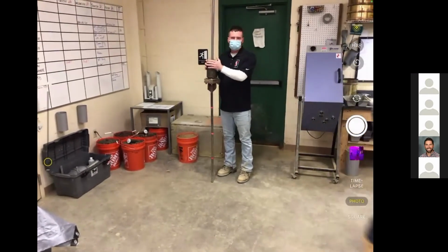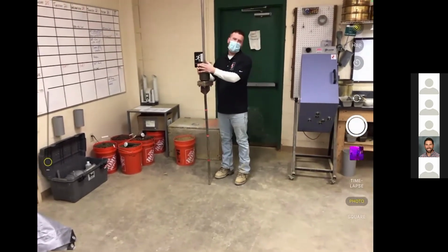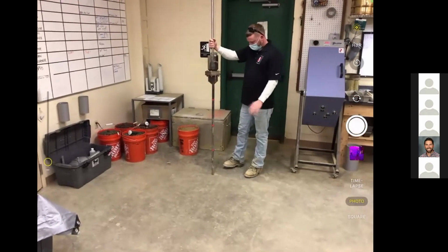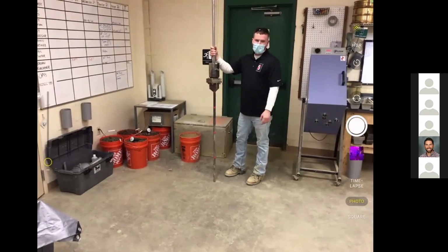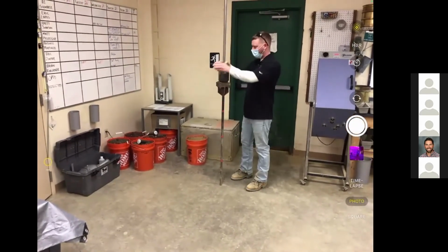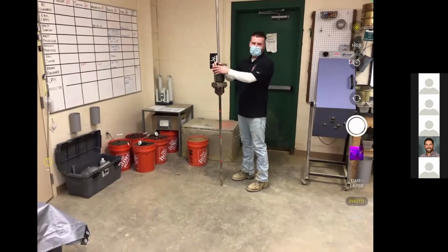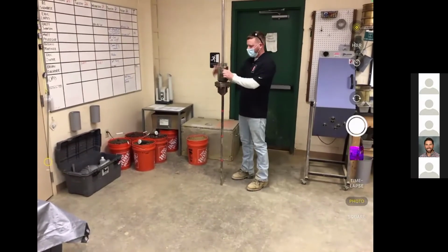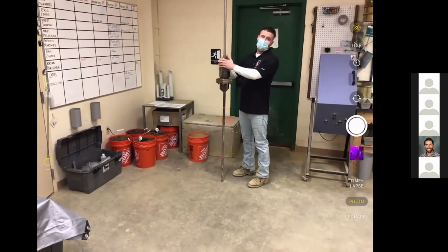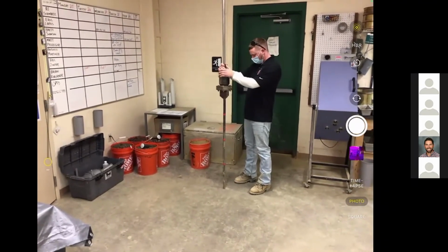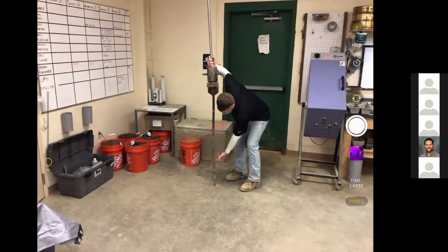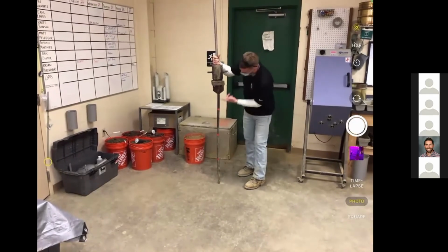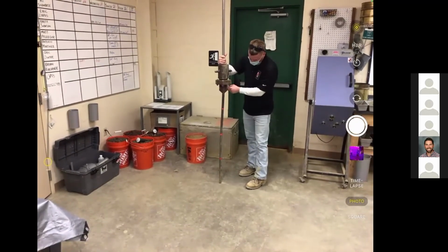The Nees drop bar was designed by Frank Nees in 1945. We still use it to this day. Not to be confused with compaction, this is for the bearing of the building and what strength we need out of the soil. So we excavate, we go in before we see rebar in the hole, before we pour concrete, and we run this test to determine whether or not the soil has the strength that it needs as it was designed. So we have foot increments marked on this drop bar: 1, 2, 3, and we can go into the 4th foot if necessary.